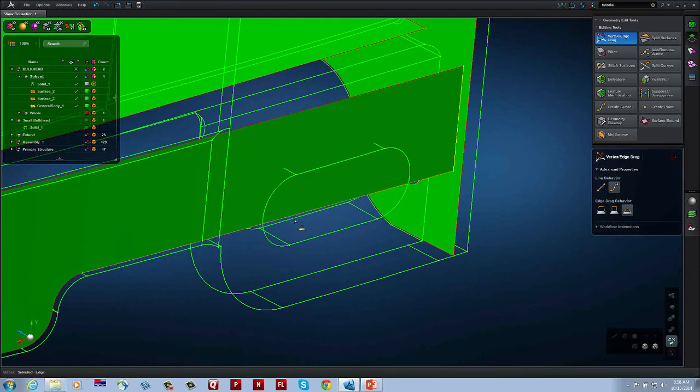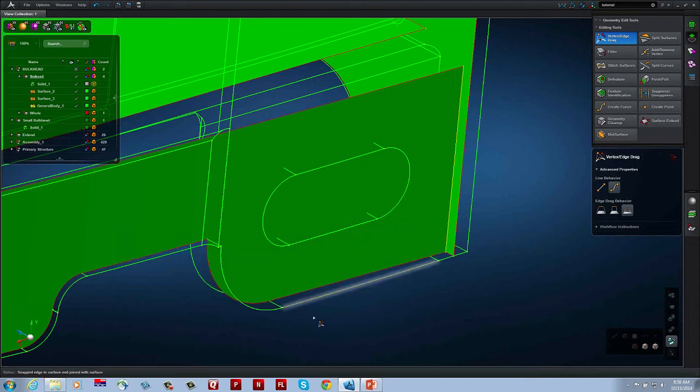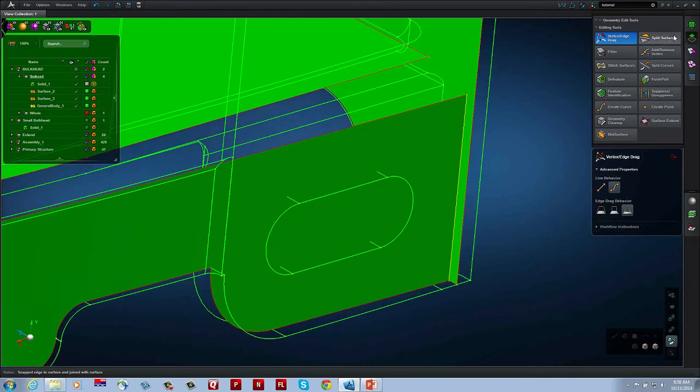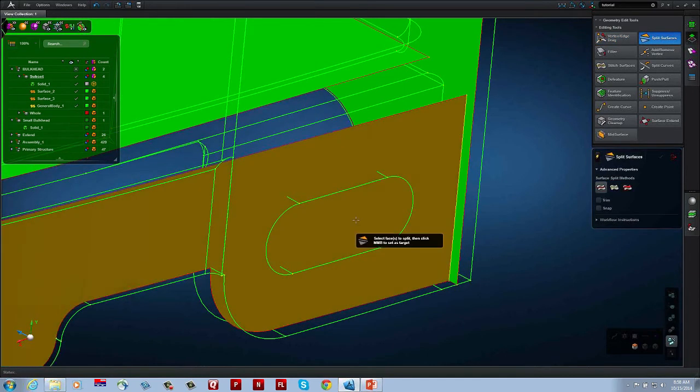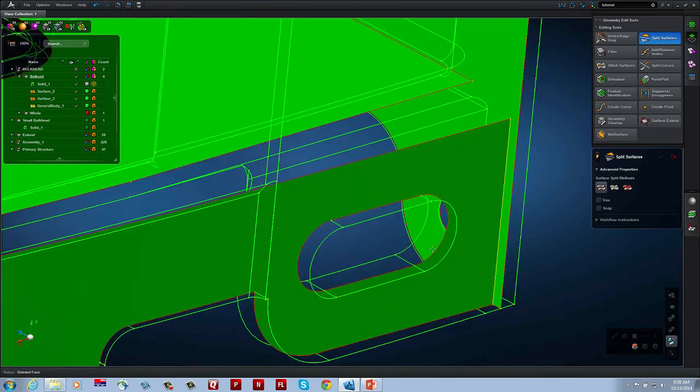So let's now drag this edge, and we're going to drag it down to one of the faces of the solid. Notice that face highlights. That lets me know I'm snapping into that face. Notice how it automatically trimmed here. Didn't trim out the hole. That's going to be an enhancement coming soon. I'm going to clip the hole by just simply doing a quick trim operation at these edges to get rid of the hole. So let's delete that, and it's gone.